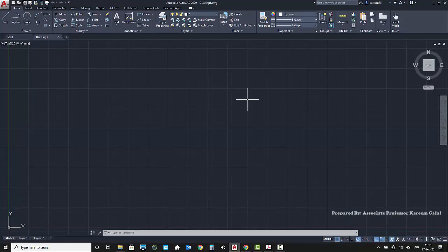Now we can see the AutoCAD drawing interface. Let us get to know it. The first part is the drawing screen, this black screen with the white grid lines. This drawing screen is called Model Space. You can see it as a tab in the lower left corner. You can draw your model at 1:1 scale. The scale or unit system differs only in the plotting or block processes.